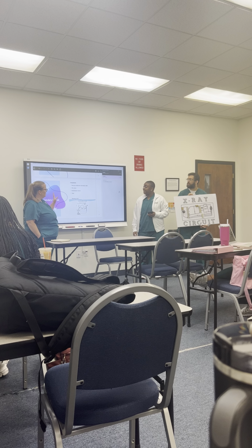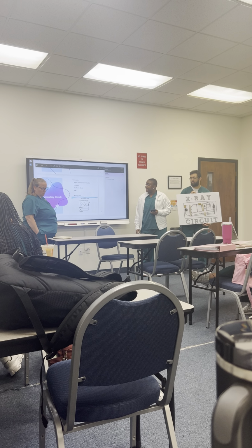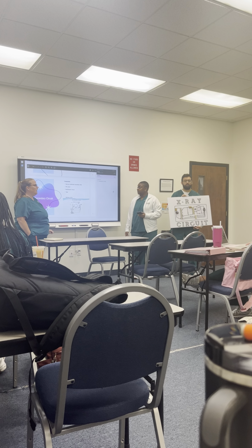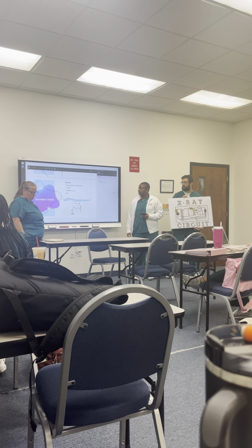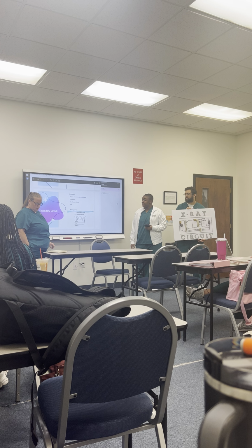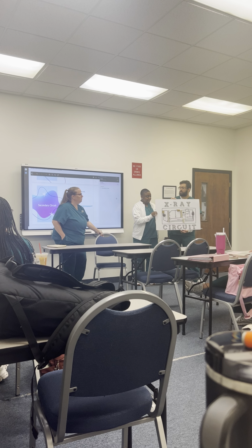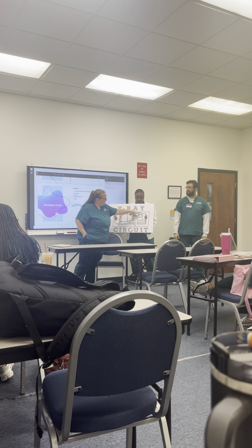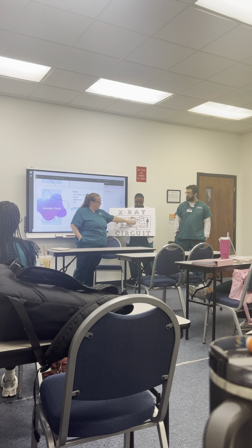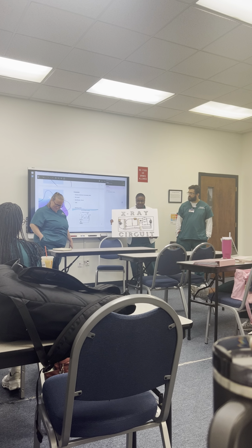And of course, like you said, it has fewer coils on the primary side and more coils on the secondary side. The mA meter measures the current in milliamps flowing through the X-ray tube during an exposure. The rectification circuit converts the AC to DC, which is required for the tube to function. The rectification is achieved using the diodes, these are the little diodes right here, and this is the rectification circuit. This is the step-up transformer, thank you. My mind drew a blank.